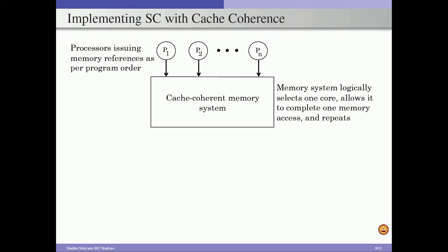So, for example, consider a bus based simple multi-core system, where we have 4 cores connected to a common bus. When each of these cores wants to get some data from the main memory or the shared cache, they place their request on the bus. But note that multiple cores cannot place their requests simultaneously on the common bus. So, they have to go through bus arbitration logic and request the bus, and the bus will be given to only one of the requesting cores. Whoever wins the arbitration places their transaction on the bus, so that the memory or the shared cache supplies the data for that request. After that the bus is released, and all other cores again compete for the bus, and whoever wins sends their request on the bus, and so on.